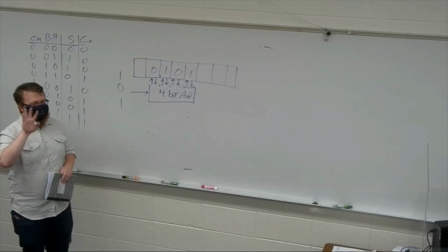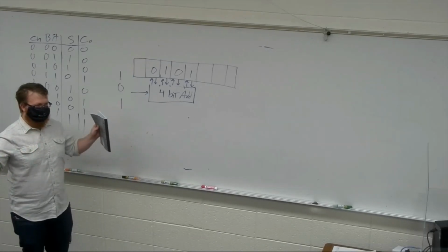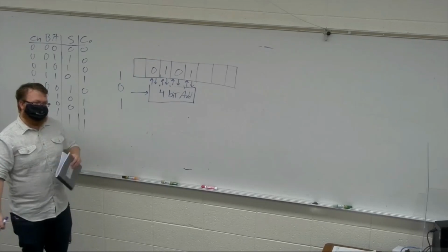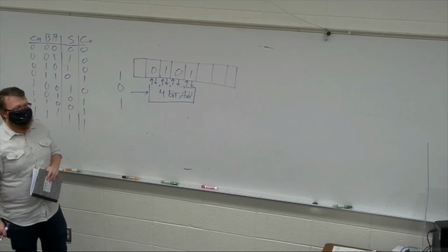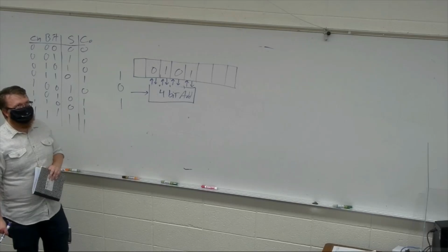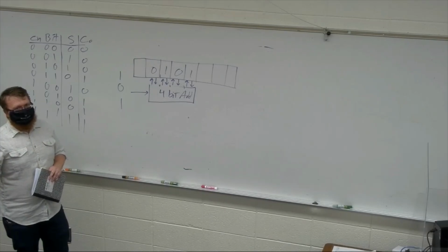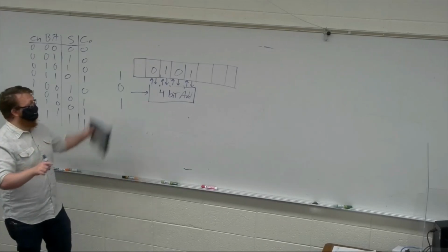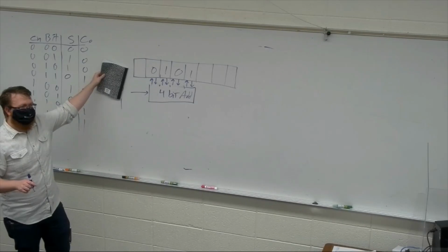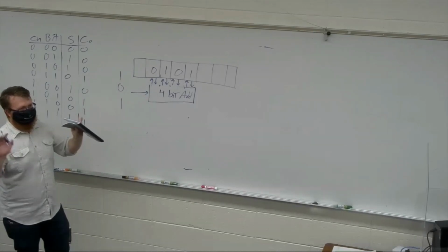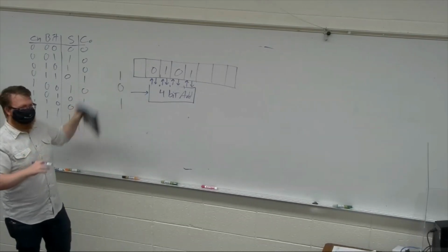If you multiply 4 bits by 4 bits, you get 8 bits at most. So if you wanted to divide it, you add 1 more on the add. Well, no, because you will never get. Oh, I see what you're saying. Into the accumulator. Yeah. So if you want to do 5 times 5, then you need the sum of those two as the output. So you want 5 bits times 5 bits, then I need 2 additional bits in my accumulator.